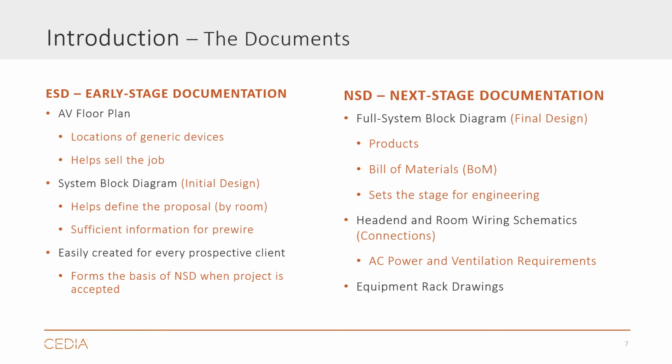Power and ventilation. How can we install our systems without first knowing the power and ventilation needed? If we don't figure this out correctly, we can either over-engineer our systems and waste a lot of money in product, or we could under-engineer it and likely shorten the equipment lifespan. The AC current and ventilation requirements can be calculated right from the schematic drawings.